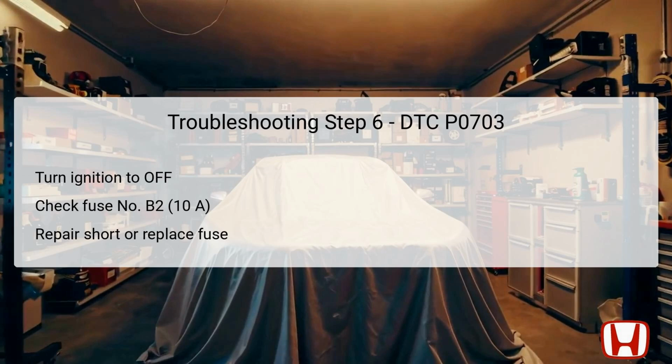If the fuse is operational, this suggests that the IG1 ACG wire also remains unbroken and functional. However, if there's a short in wiring between the brake pedal position switch and the number B2 fuse, repairs would be necessary to restore proper function. Identifying the status of this fuse is essential for ensuring that the electrical circuit related to brake operation is safe and fully functional.